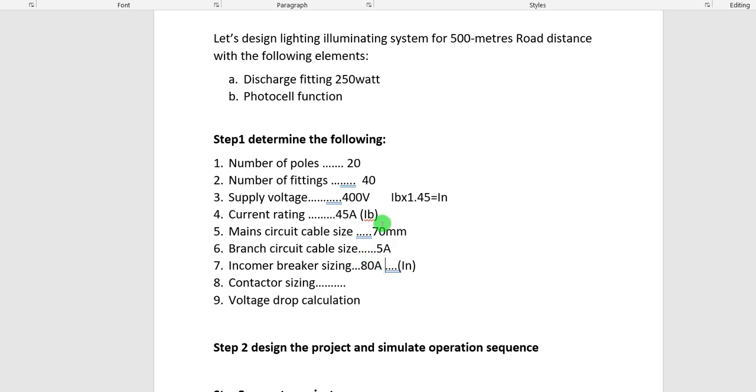You may not understand this until you do it two or three times, so that you know the ranges of MCB and ranges of cable. If they are not close, you will know that this cable cannot reach a temperature that can respond to this fault. As you progress, you will know better.